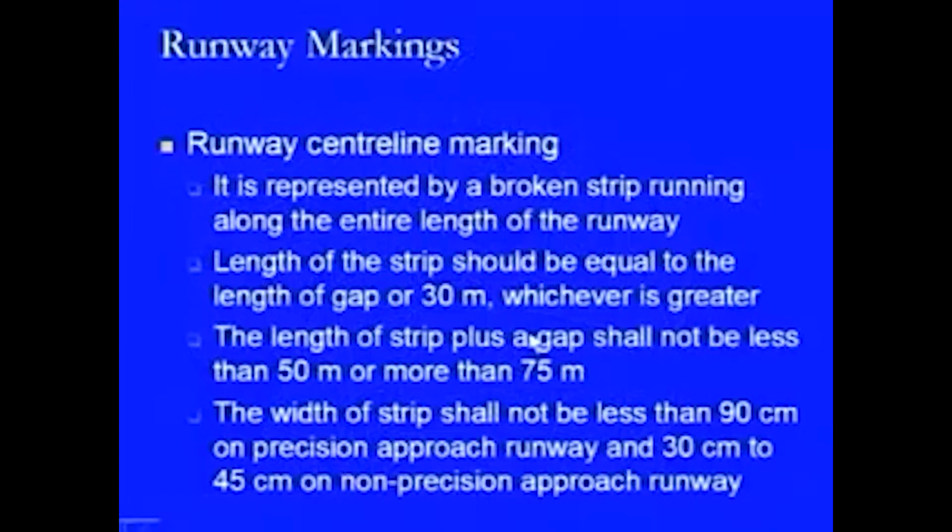The width of the strip shall not be less than 90 centimeter on precision approach runway strips, and 30 centimeter to 45 centimeter on non-precision approach runway strips.